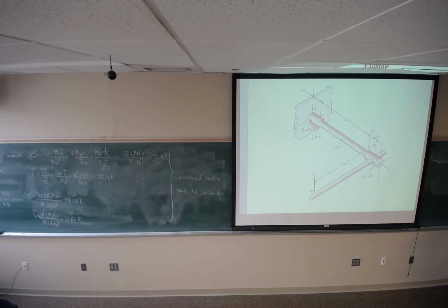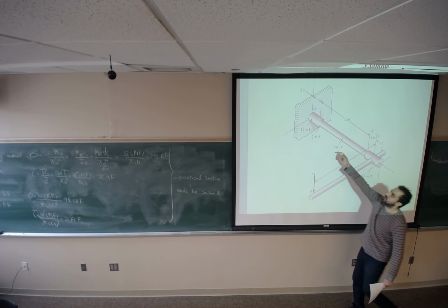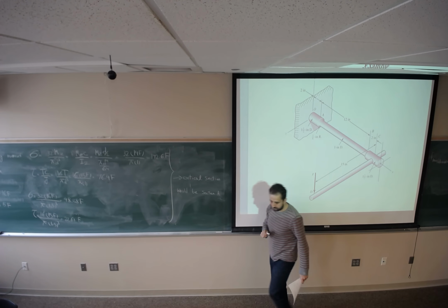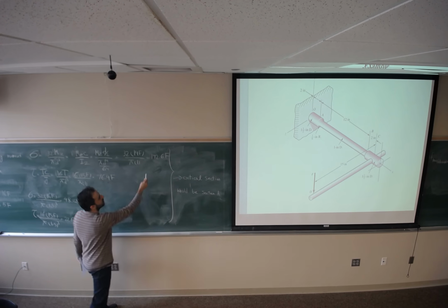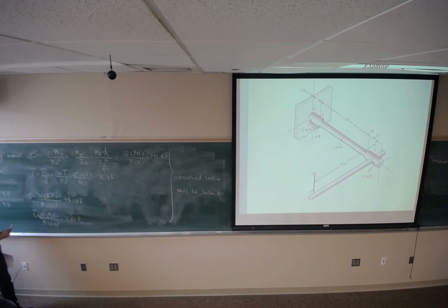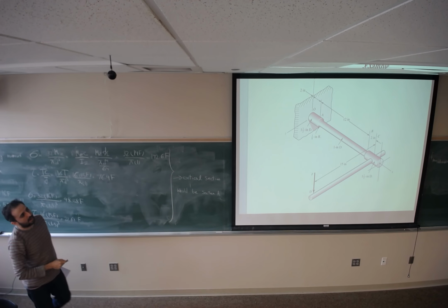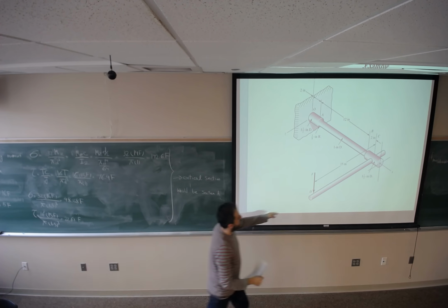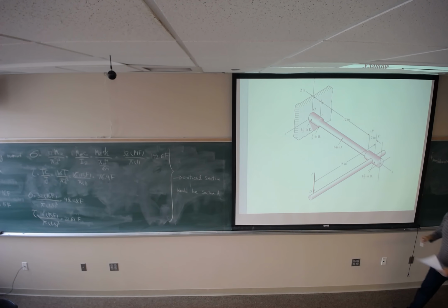If it was made of brittle material, I would have had to consider the stress concentration factor for these two, which occur at section A. And if we had dynamic loading, if the load was varying with time, then I would have had to look at the stress concentration factor, but it's out of the scope of this example. We will look at it in chapter 7.